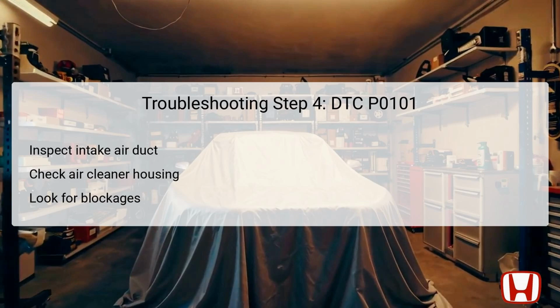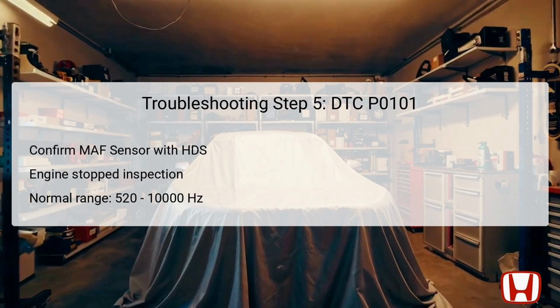For the fifth step in troubleshooting DTC P0101, it is important to confirm the MAF sensor readings using the Honda Diagnostic System, HDS, while the engine is in a stopped condition. This initial test isolates the sensor's readings, focusing solely on whether it produces expected data under no load. The normal frequency range for the MAF sensor is between 520 and 10,000 Hz. Any readings falling outside of this range suggest an issue with the sensor itself or its wiring.